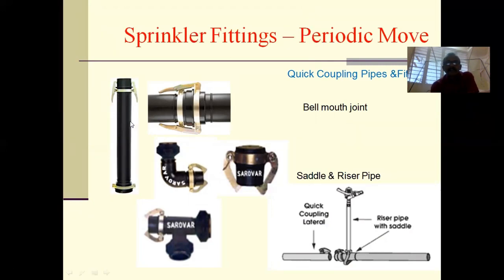See here how when two pipes are connected together, how it appears. And this pipe will have a washer at this end. And this washer has the ability to expand, and when pressure is increased to its sufficient level, say 25 meters to 40 meters, then leakage would get arrested.